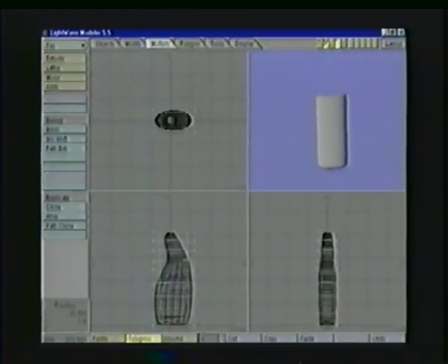That's because the top of the bottle is going to go up into the neck of the spray bottle part that twists on. We don't need a polygon on the top. And when we subdivide it, it won't be just one poly, it'll be many. So I'm saving myself a number of polys on the top right there. Not only that, but it's going to give us a different shape than if there was a poly there when we start bending.